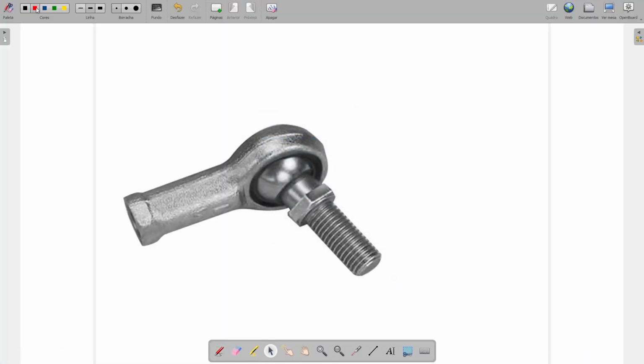Okay, so you see that in a ball joint connection, we also have the ball stud, that is this part, and then it has a thread because we usually apply a bolt pretension, so we will have a nut here, and then we will have the other part that is being connected here, just like in our example. And then you see that the ball stud has this spherical shape here, and then we have another part that needs to have a housing that goes around the ball stud.